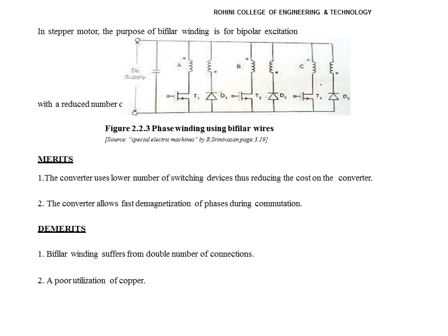When T1 is turned on, the DC current passes through the phase winding A. When the device is turned off, the energy stored in the magnetic field is fed to the DC source through the winding A dash and diode D1. The three devices operate in a sequential way depending upon the signals obtained from the rotor position sensor, and the chopping signals for PWM techniques are obtained from the control.